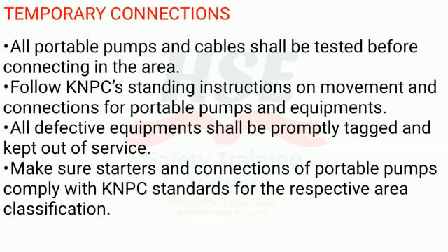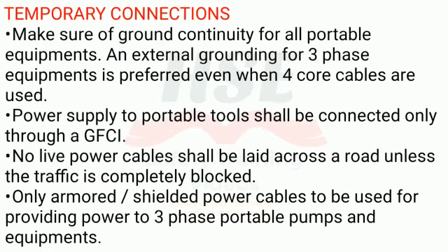Follow KNPC standing instructions on movement and connections for portable pumps and equipments. All defective equipments shall be promptly tagged and kept out of service. Make sure starters and connections of portable pumps comply with KNPC standards for the respective area classification. Make sure of ground continuity for all portable equipments.